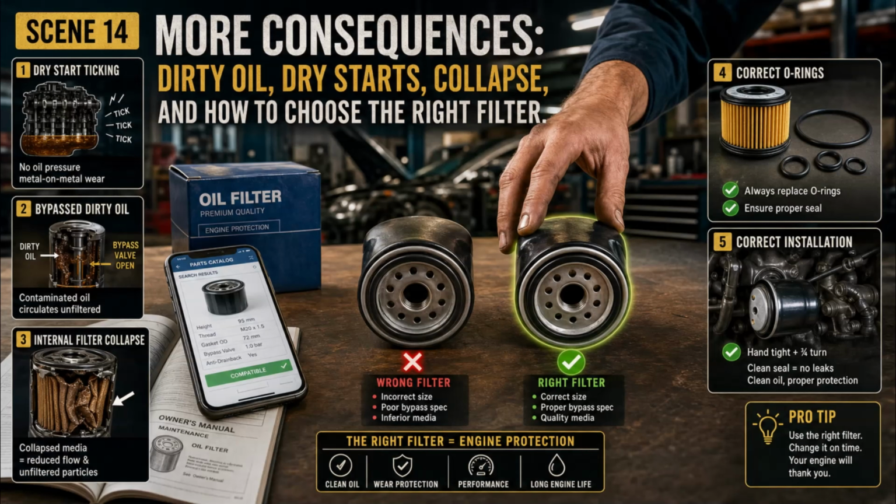That oil film is extremely important. Inside the engine, metal parts move very close to each other at high speed, and oil creates a thin protective layer between them. Without enough oil pressure and flow, bearings can overheat, score, or wear very quickly. A wrong bypass valve can let dirty oil circulate more often than intended. A missing or poor anti-drainback valve can cause dry start symptoms in some engines, meaning oil pressure may take longer to build after the car has been sitting. You might hear ticking or rattling for a moment after startup.